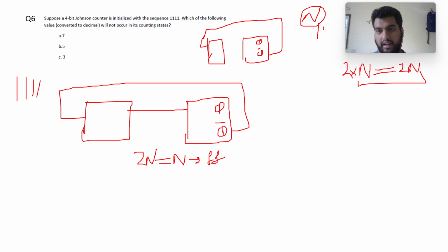For a ring counter we will have n states. So here we have this twisted ring counter, it is initialized with 1111. As it is initialized with 1111, my Q bar will be 0. So in the next cycle my input will be 0 to the first flip-flop, and that will go to the next cycles, and so on. Initially it was 1111. In the next clock cycle it will be 0, it will come here, and all other ones will just right shift, 0111.